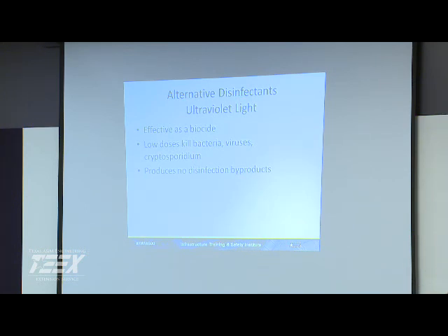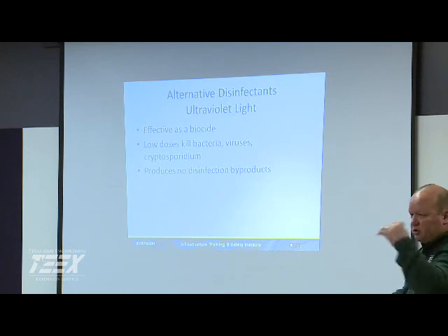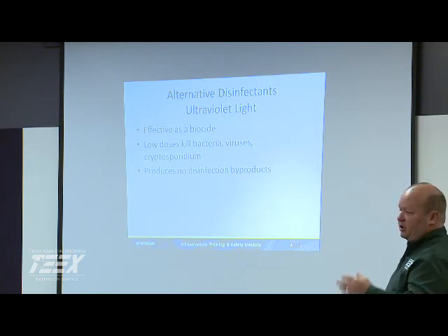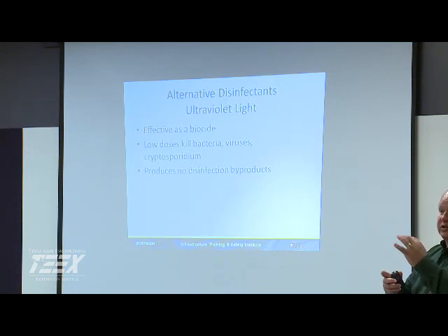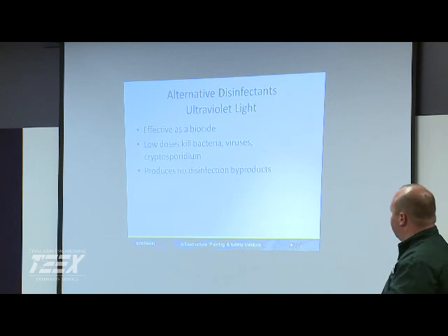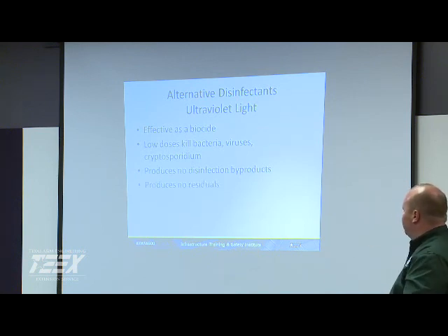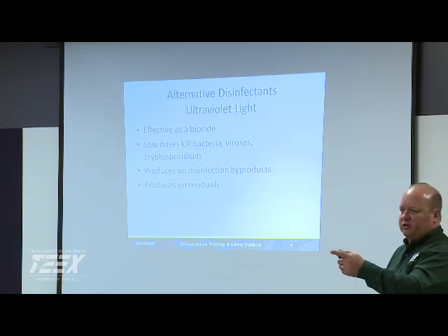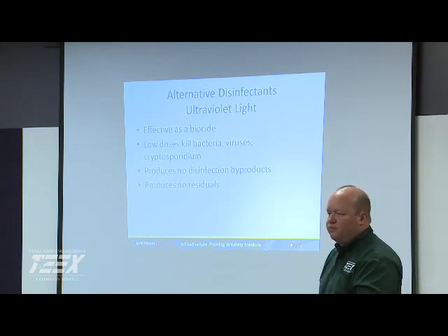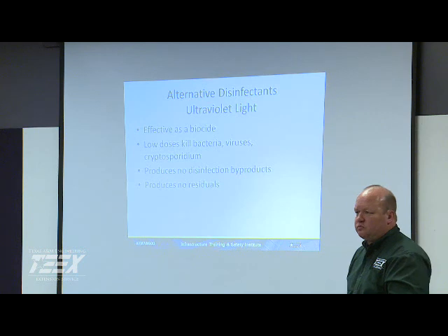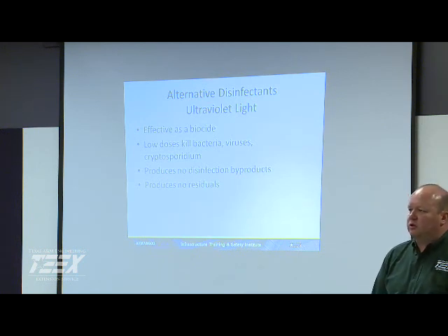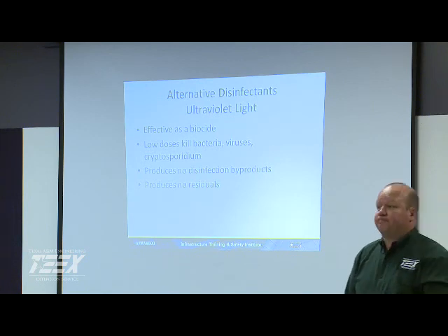You don't have any disinfectant byproducts because it's not a chemical reaction, it's a physical reaction, and it's actually denaturing the DNA in the cells, the UV, and that's what happens when we get skin cancer from sun exposure. It's mutating our DNA. So we're making them unable to reproduce using UV. I don't know if anybody's using UV on the water side. We've got one system that has it installed, and we're looking at not using it anymore because of the energy costs.